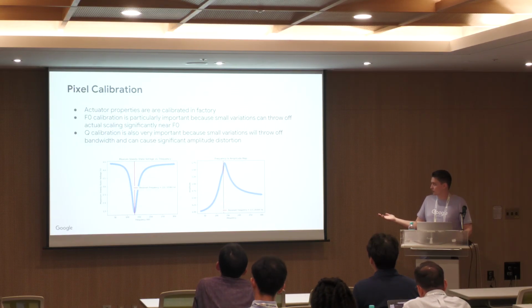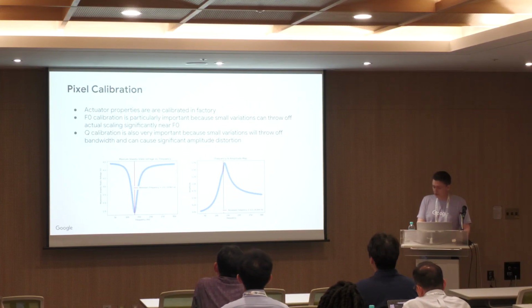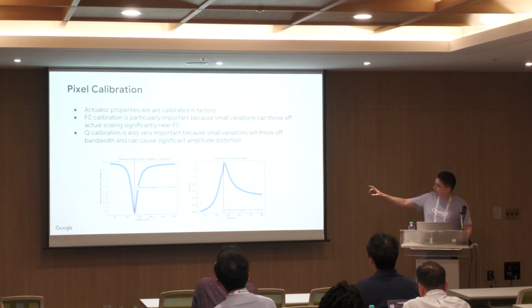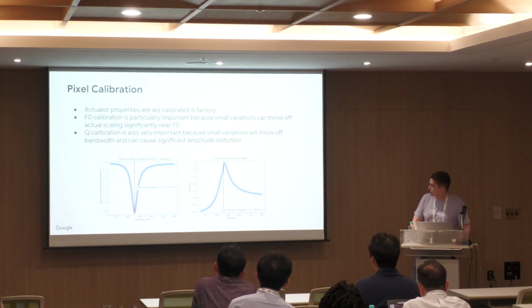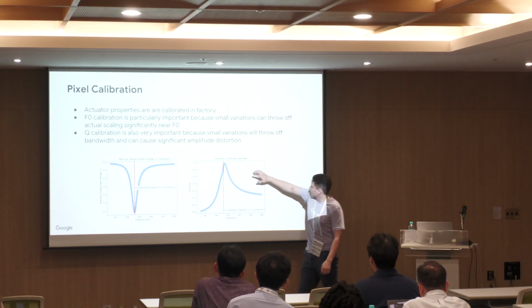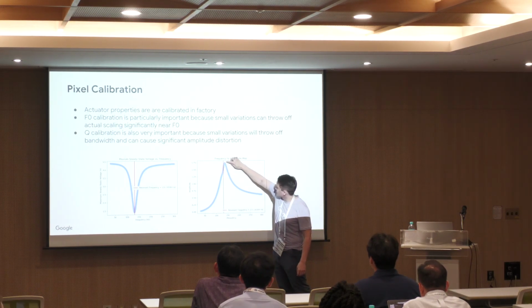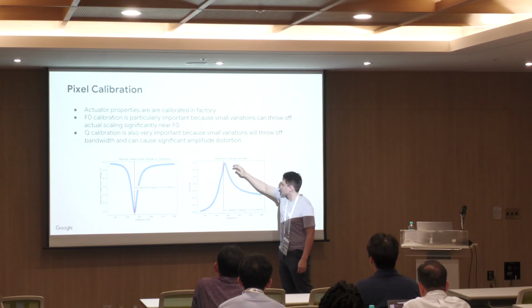So the expected resonant frequency would be centered around 130 hertz, but this device's actual resonant frequency is 131.16 hertz. I'm not sure if you can read that. And you can see that even this tiny 1.1 hertz change really throws off the frequency to output acceleration map. Right here is where it crosses, and here's the expected maximum amplitude.